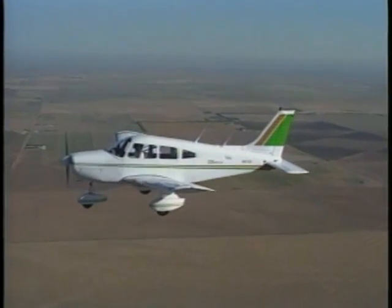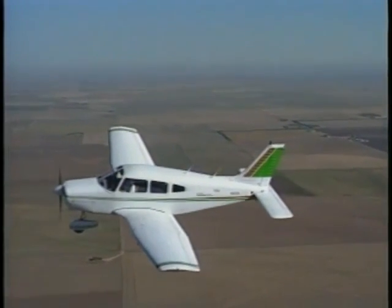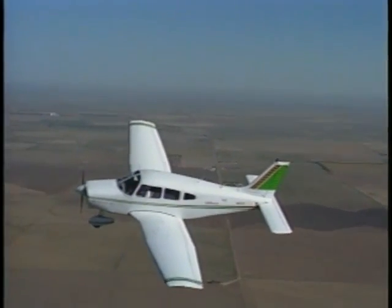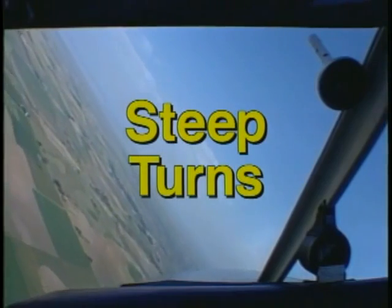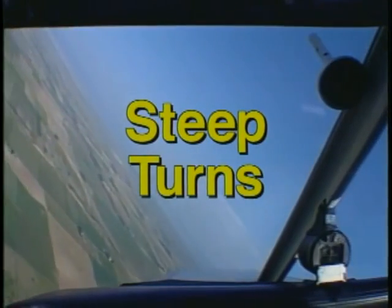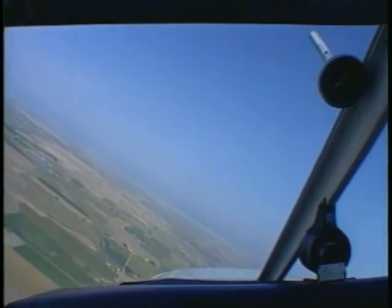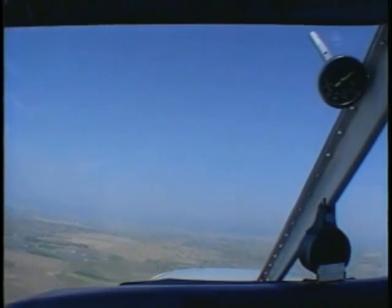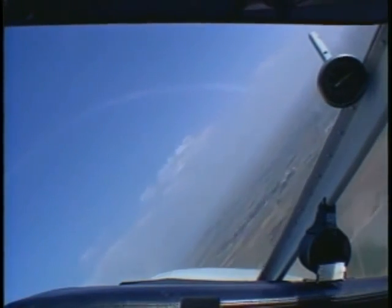As you progress in your training, you will develop the ability to precisely control your aircraft by learning how to execute a number of maximum performance maneuvers. The steep turn develops your ability to accurately control the airplane in a maximum performance turn. You'll perform the maneuver at a constant altitude using a bank of 50 degrees. This maneuver can be performed to the left or right.